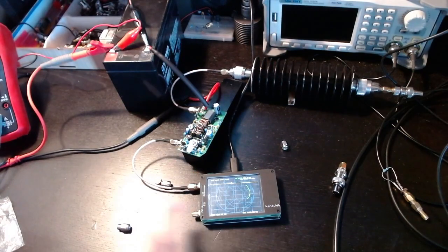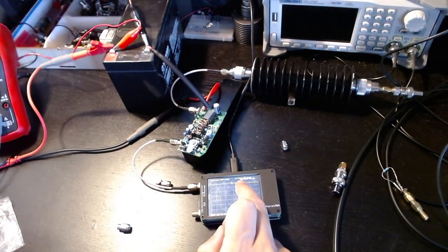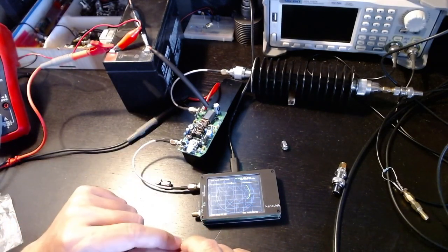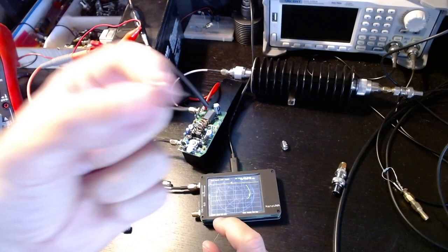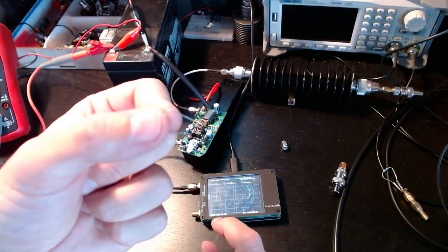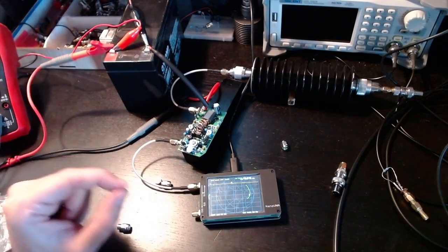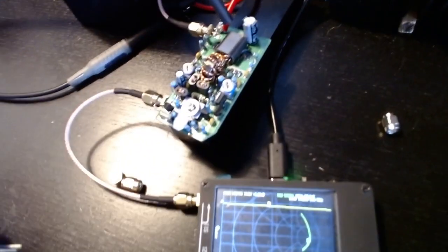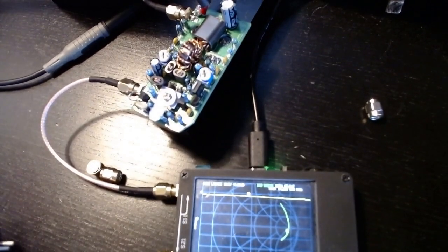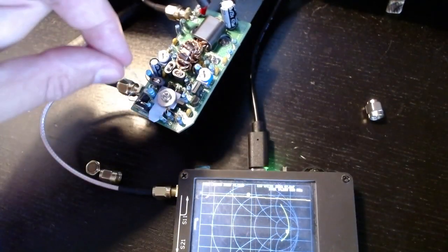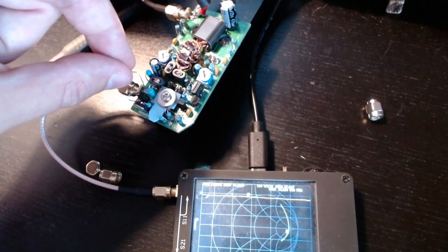And the fact is that if you put in parallel 280, which is the input impedance of this amplifier, with 55 ohm, you get something like 48. I made the calculations earlier. 48 ohm, so slightly below 50, but okay. And so let me show you what happens if I put this resistor in parallel with the input resistance of the amplifier. So let me try to do that.